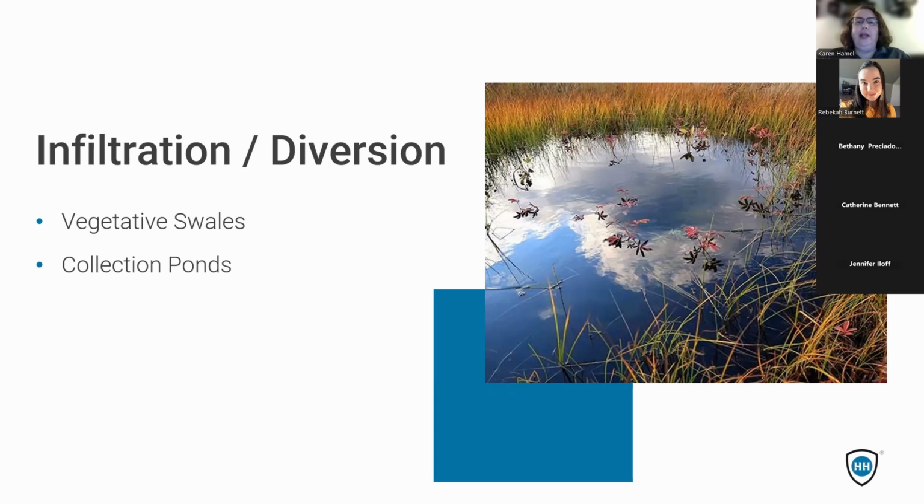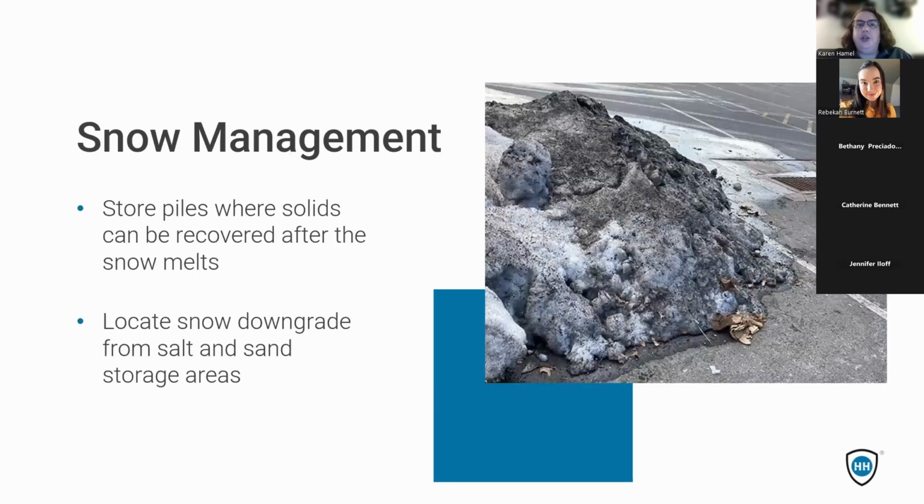Is there an area that isn't paved that you can turn into a retention or detention area and channel all of your outdoor fluids there, so that you've got that next step before it would be discharged? It's easier to clean up that small area than to try to clean it up once it gets into the river. Are we managing our snow piles?